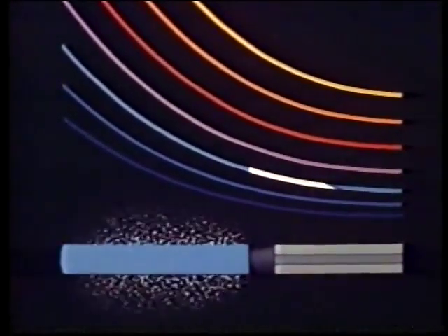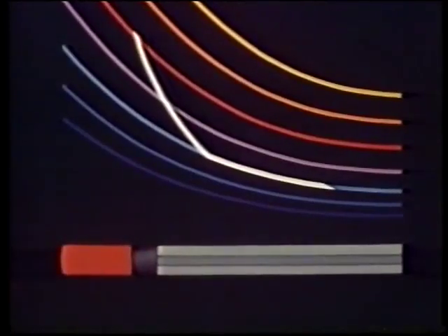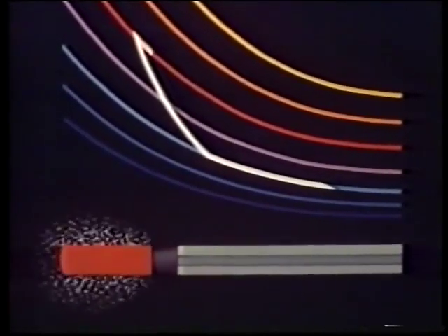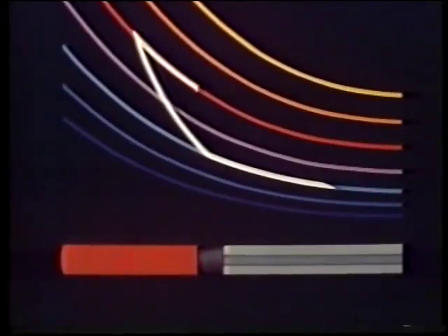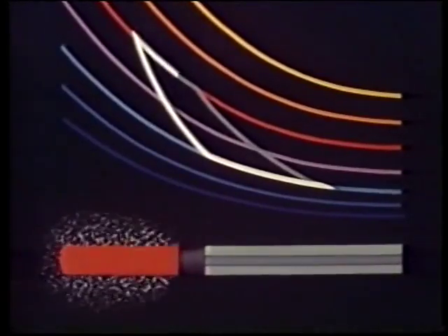Let's see what this means in terms of the familiar PV diagram. Isothermal compression, compression along an isotherm. Adiabatic compression, temperature increased to another isotherm. Isothermal expansion, expansion along this upper isotherm. And finally, adiabatic expansion to bring the temperature back to the original isotherm. And so on. And this area of the PV diagram represents the net work done during a cycle.